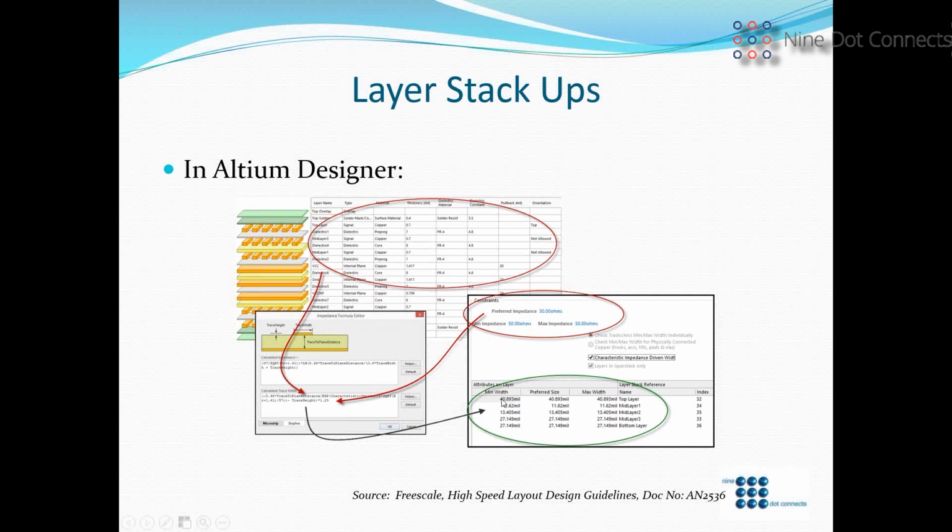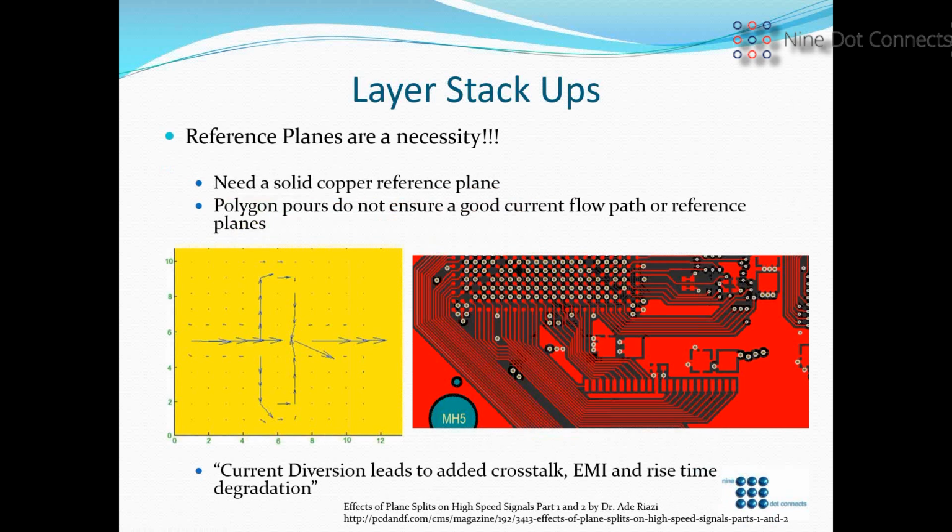Now, with that being said, you'll notice that this over here, if you can see, it says 40 mils. That's really outrageous, right? We're used to working in 8 or 10 mil traces. If we're going through FPGAs, it's going to be even smaller than that. So what happened over here, and that brings us to our next point, all right? Reference planes. We've got to have reference planes. That means that, because I showed you at the very early onset a picture that's very similar to this, under high-speed designs, you have a lot of current that's flowing directly underneath that signal, okay?